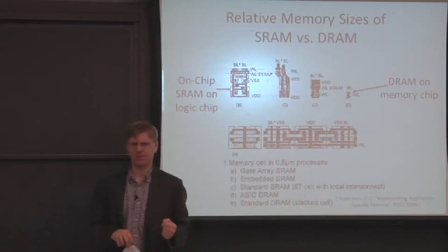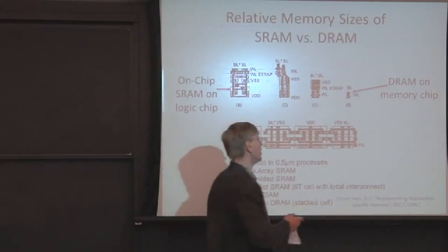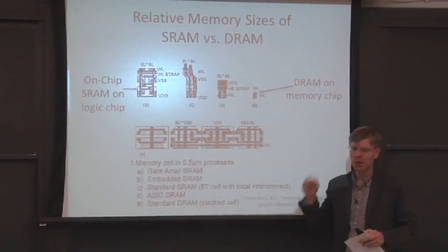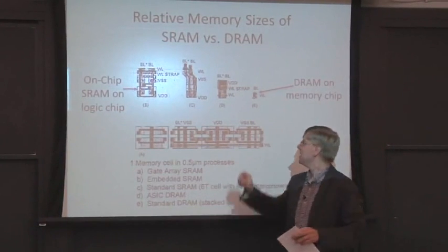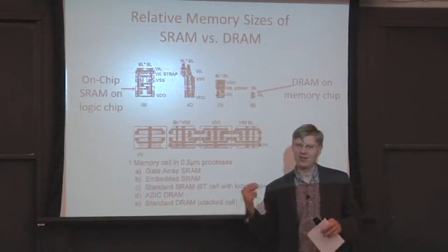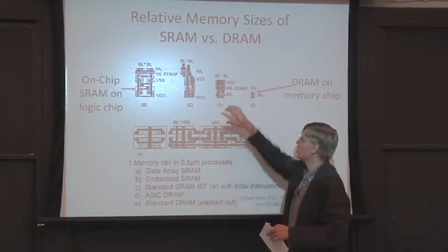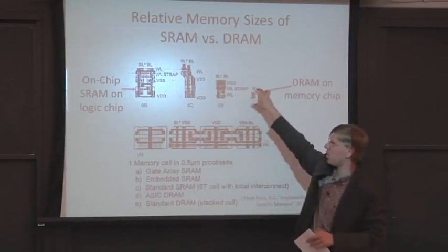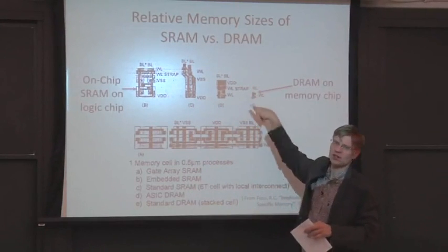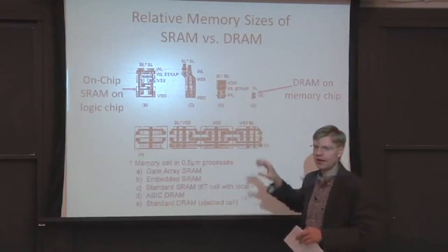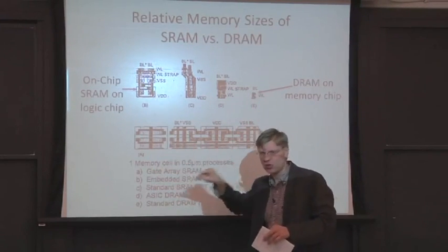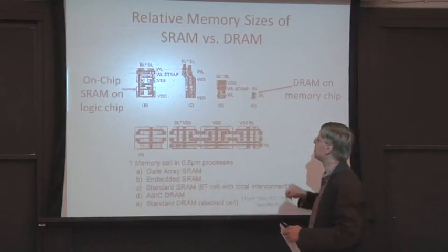And it's pretty big. Let's contrast that with this one over here. We have DRAM on a memory-specific process, and it's tiny. It's not only 1 transistor versus 6 transistors, it's actually more than 6 times smaller, because they can optimize it and go into the Z dimension, into and out of the board, because that trench capacitor goes down into the substrate.